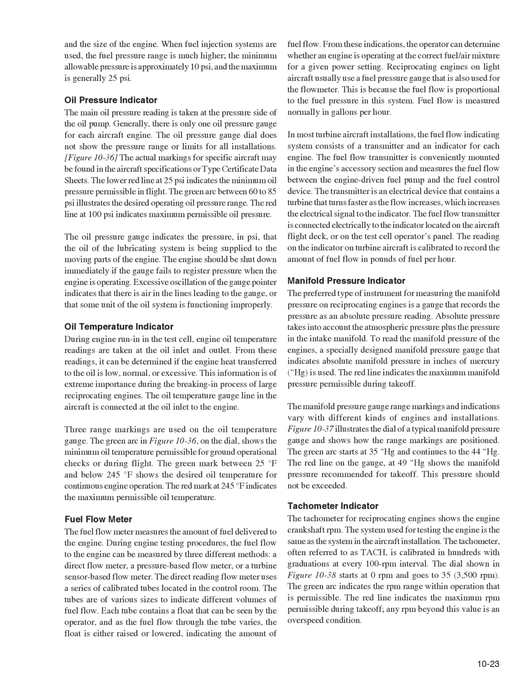The engine should be shut down immediately if the gauge fails to register pressure when the engine is operating. Excessive oscillation of the gauge pointer indicates that there is air in the lines leading to the gauge, or that some unit of the oil system is functioning improperly.